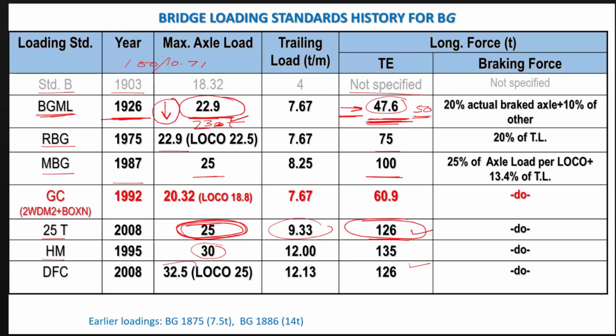If any design criterion is later lost, then it will be very dangerous. So when I was Deputy Design, I made a practice of asking for an interaction ratio within 0.85. That way we can make our structure safer. Yes, sir. Thank you so much, sir.